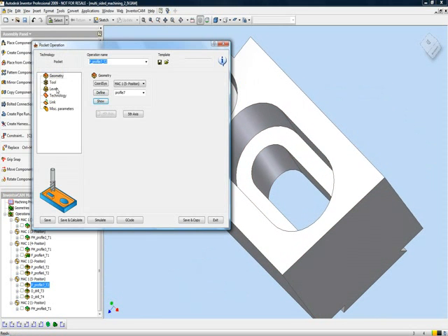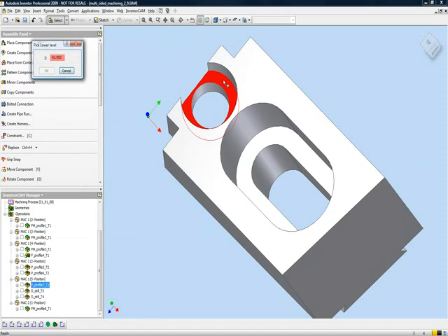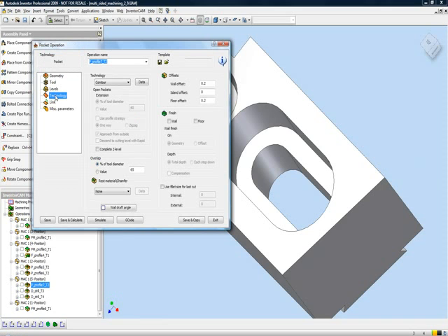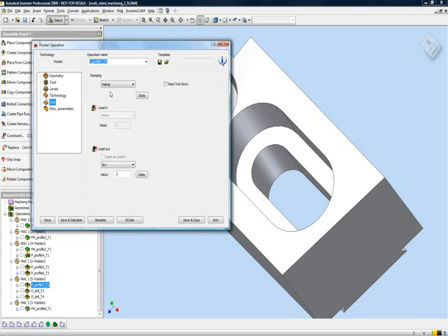and my tool will be again the 10mm end mill. My levels, my pocket depth will be up until the floor over there itself, again using technology of contour with a wall offset and a floor offset, and a link in of helical and a lead out of arc.